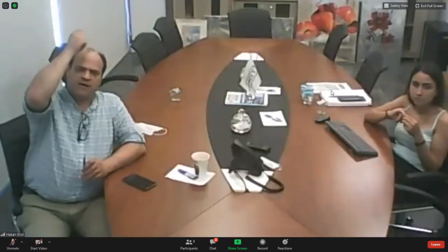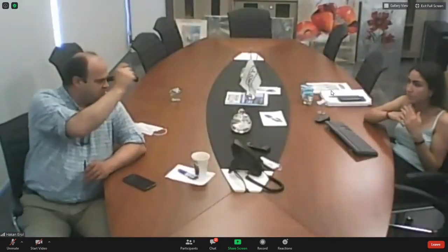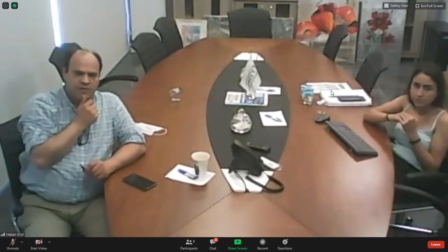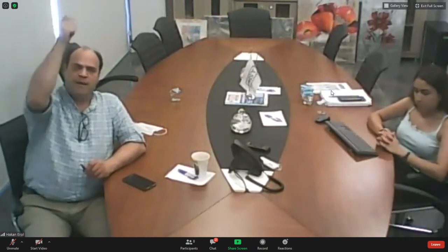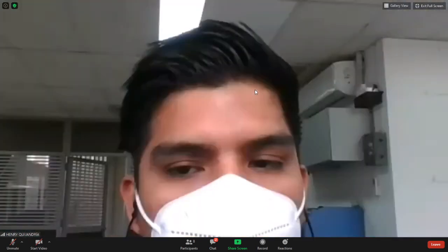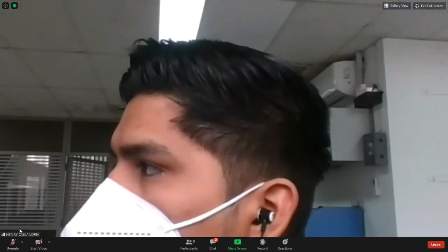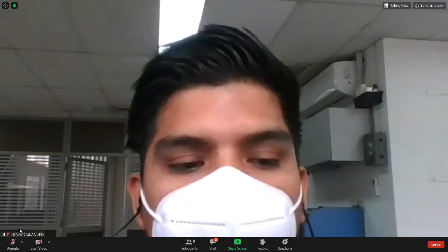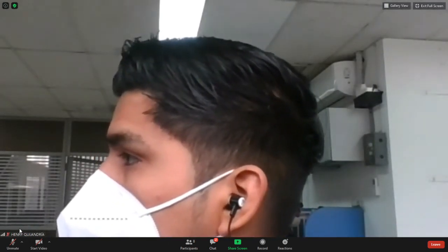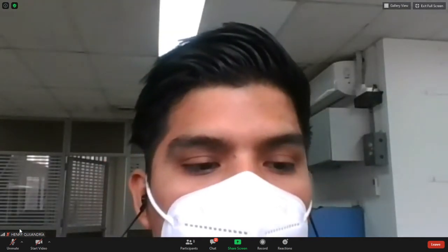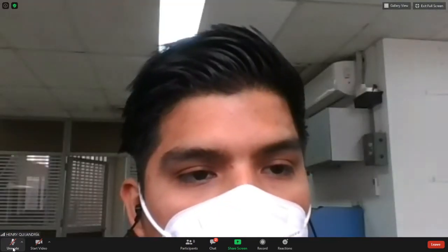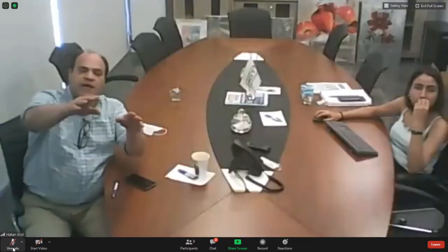They make a scan test. When they fix the HEPA filter, they make a leakage test. We made the particle counting after installing the filter.